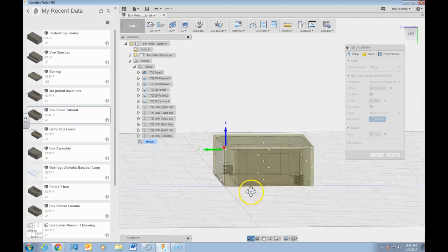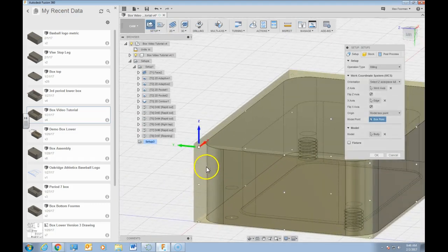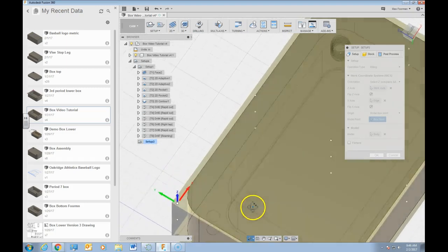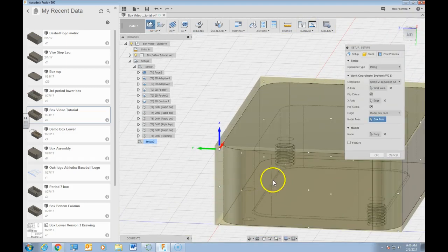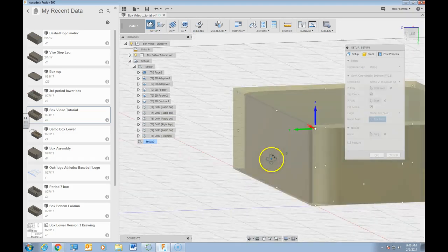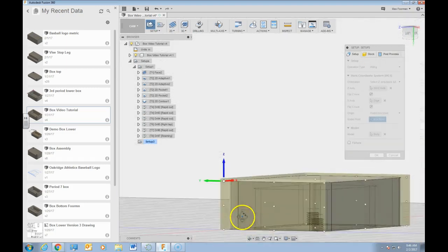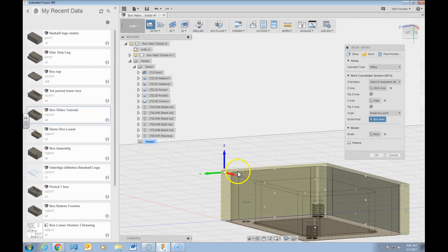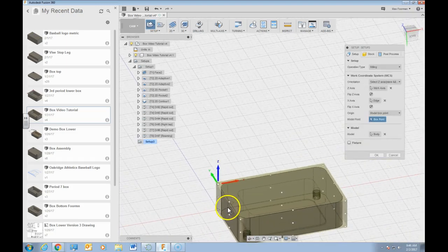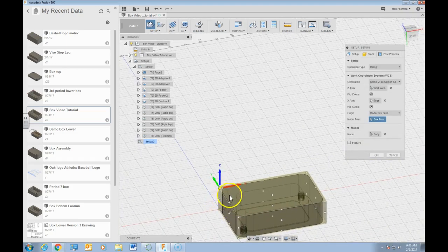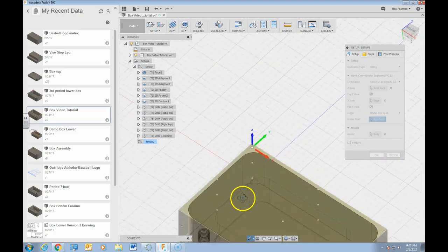We're going to have to do a little bit out at the machine to tweak to get this here, but that's not going to be too difficult to do. But yes, I want my origin now to be aligned to a face that I've already machined, and ultimately it isn't dependent upon the stock up here, but more likely on the position relative to there, up to there, that I've already established. But anyway, for now, that's what I'm going to claim my stock origin to be.